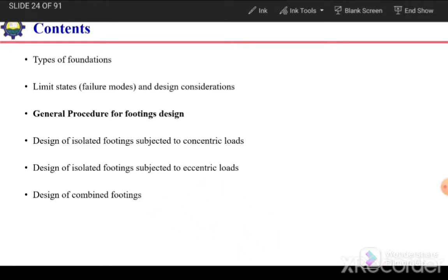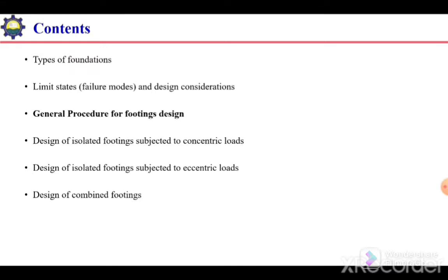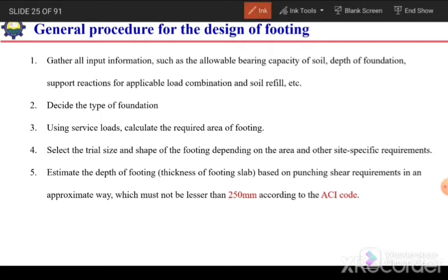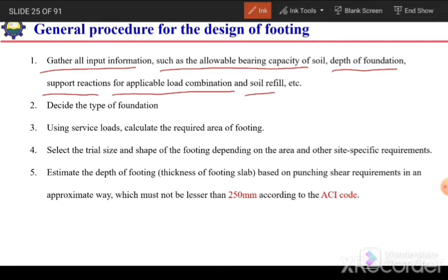In the previous video, we discussed the limit states and design considerations for concrete footing. In this video, we will discuss the general procedure for footing design. First of all, we need to gather all input information such as the allowable bearing capacity of the soil, depth of foundation, support reactions for the applicable load combination, soil refill, and surcharge.